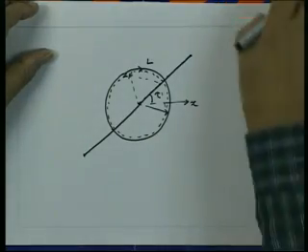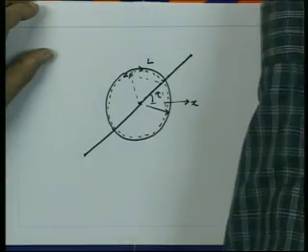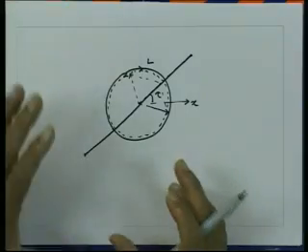So, this problem essentially explains how a linear polarization can be generated by two orthogonal states which are two circularly polarized waves. The concept can be extended now to any other polarization. The analysis would be exactly on similar lines. So, you can write down the Ex, Ey, and you can write down El and Er, equate the components, and then from there you can find out the relation between El and Er.